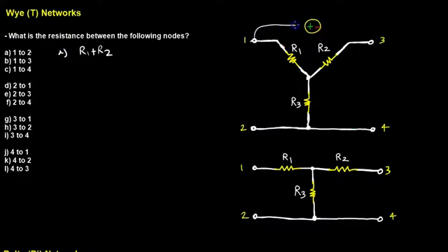I'm going to connect these up, and again, some current's going to flow. If we trace it through, we'll see that it cannot flow through R3 because again, this does not close a path. There's not a closed path for the current to flow through. That is one of the rules in electronics that you need to remember: there needs to be a closed path for a DC current at the very least to flow through.